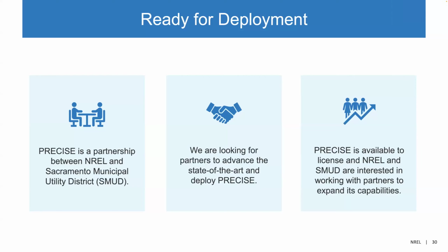Yeah, spot on, Killian. Also, since the 2018 IEEE 1547 standard came out, volt-var set points are now a requirement. So providing voltage support is a requirement. The question we had to answer internally was, do we just require a standard volt-var set point for every single installation and potentially subject every single installation to curtailment at certain times of the year, or do we just use it where we need it?